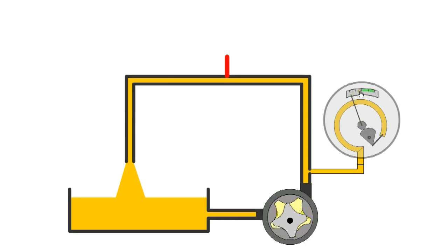If we close the valve, the flow of oil is restricted and we start to build pressure. If we close the valve further, we see another increase in pressure. We cannot close the valve fully because this is a positive displacement pump. If the valve is fully closed, pressure will rise sharply and something will break. Usually a pressure relief valve is used to protect against this situation. When the valve is opened, there is no restriction and we lose oil pressure.